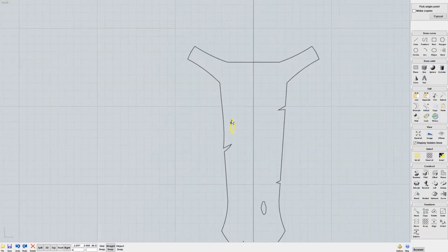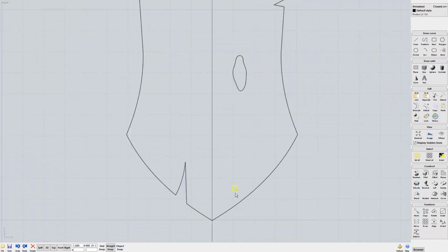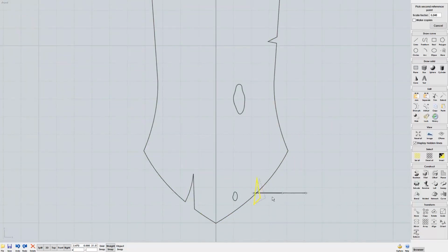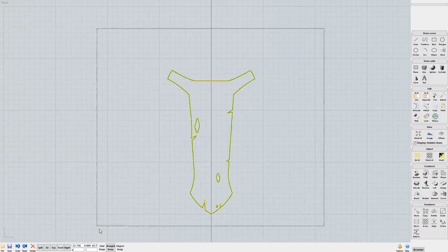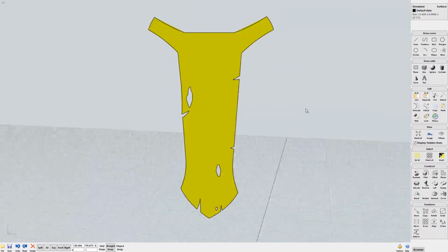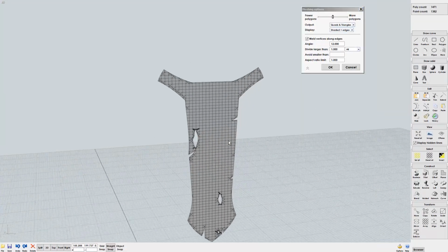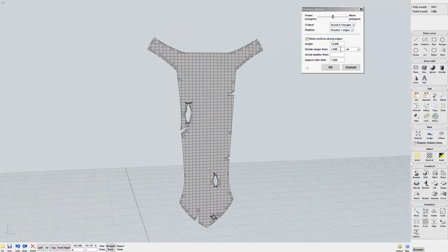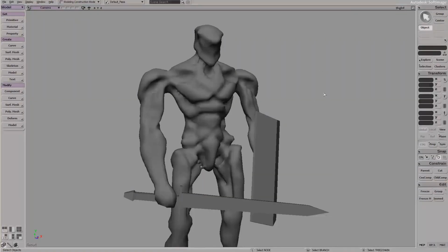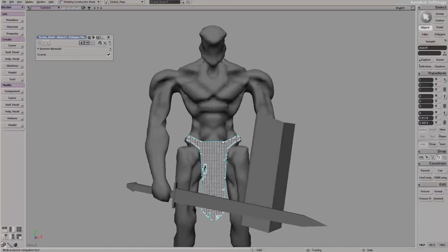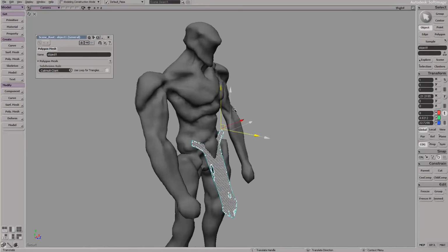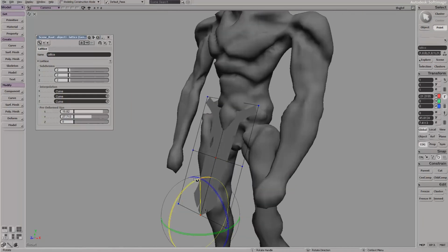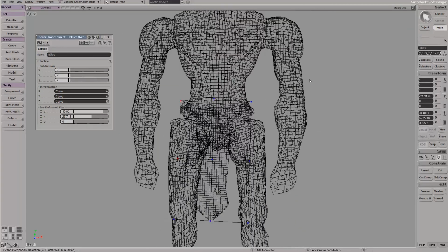Now, the reason why I'm in Moi doing this is because it's very easy, at least for me, to use those splines and draw curves to make a simple torn cloth like that. And when you export that from Moi, by setting aspect ratio limit to 1 on the OBJ export, you can keep your topology, you can keep the density even, and also you can keep them more squarish, right? So the shape of each polygon is closer to square, which is good for the simulation.